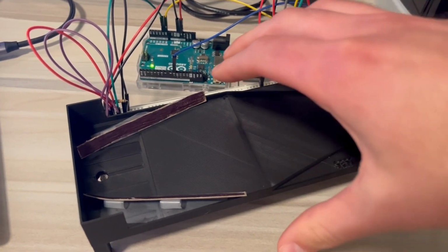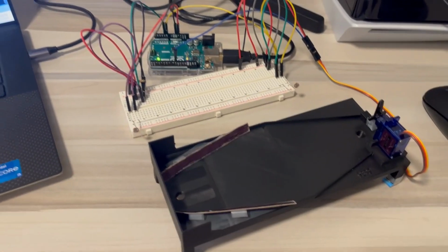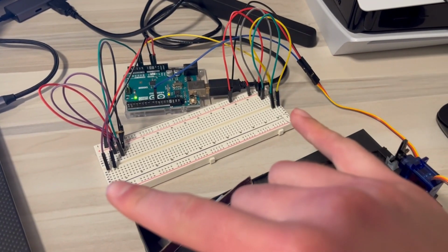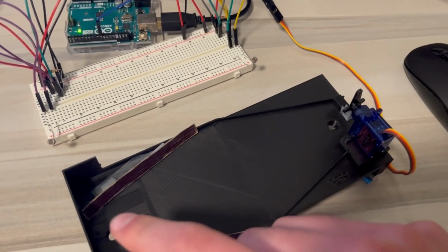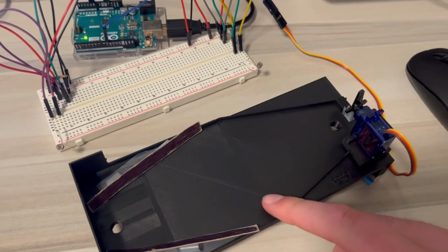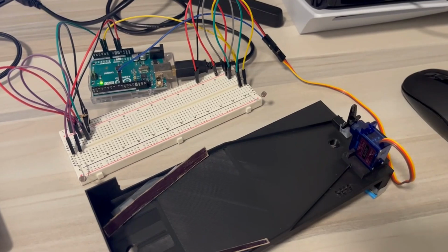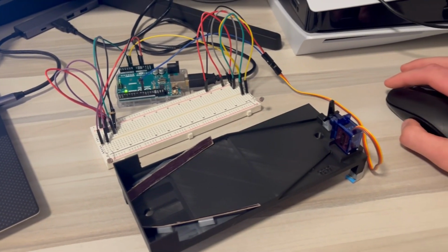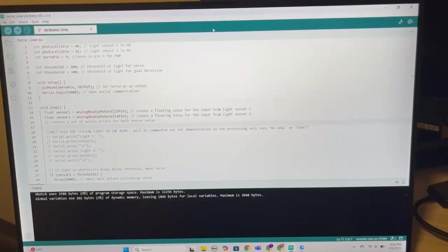As you can see, when I remove this soccer simulation stand, my circuit is somewhat generic, but consists of three main components. First, two photoresistors here near my fingers, which are then placed inside of each hole on the simulation, and a micro servo. Together, this allows for sensing and actuation between my circuit for the ball to be kicked and scored, which is then reflected on the processing window as demonstrated earlier.